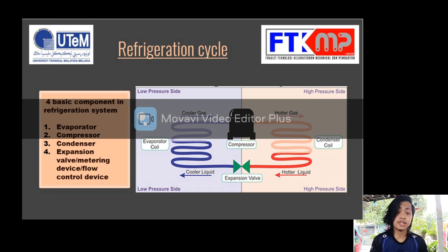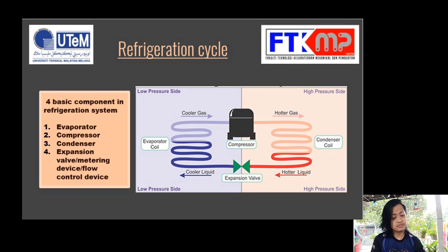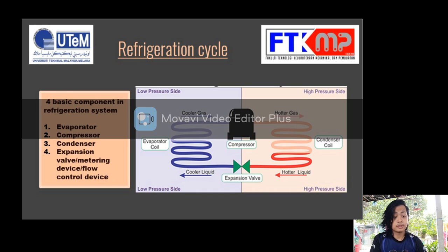It's called the cooling effect. In the expansion valve, pressure has been reduced, dissipating heat, cooler than the fan flowing around. In the evaporator coil, refrigerant absorbs heat from warm air and reaches a low boiling point. The refrigerant vaporizes and absorbs maximum heat.